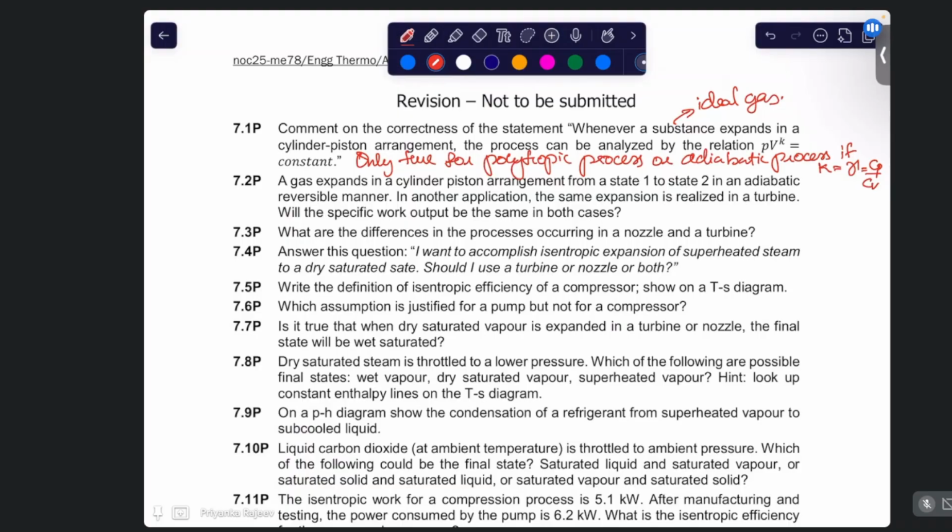Okay. So a turbine is usually an open system. It is taken as an open system with flow work and some change in kinetic and potential energy. So the device might be operating at a different exit pressure, or it will have some irreversibility in real practice. But a typical turbine has no such boundary displacement like in a piston. So they directly convert flow enthalpy into shaft work, right?